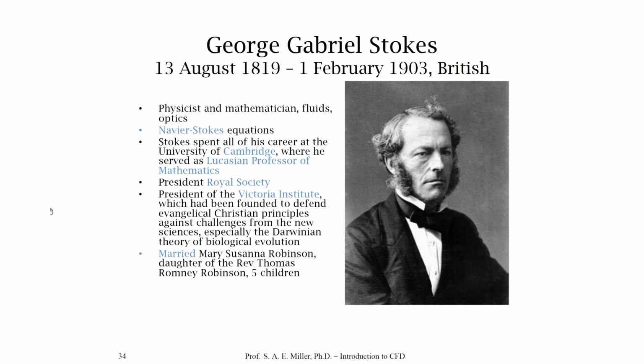A Stokes flow is a flow which creeps along at very slow speeds, where the nonlinear term in the Navier-Stokes equations drops out for an incompressible flow. He used these solutions to study swinging pendulums, and he formalized and understood the relations between the first and second coefficients of viscosity. That's Stokes' postulate, the relation between the first and second coefficients of viscosity.